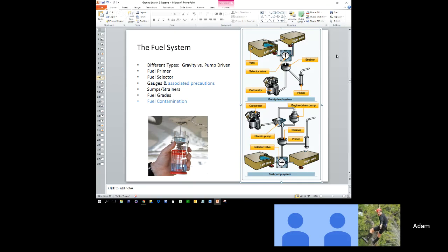But very simply, if you could only inspect a few things during your aircraft pre-flight, this is one of them. The good thing is water, having a higher specific gravity and being heavier than fuel, is going to travel all the way to the lowest point of the fuel tank, which is where the strainer is installed. And you're going to be able to very easily inspect for it.